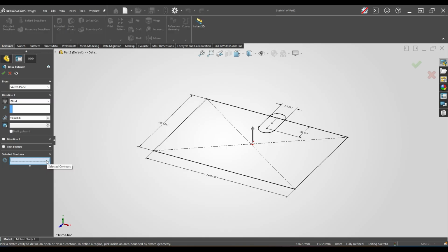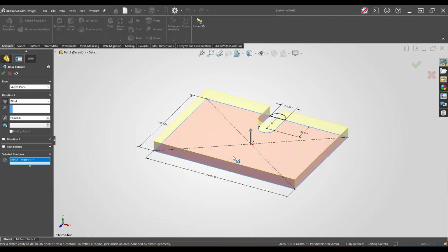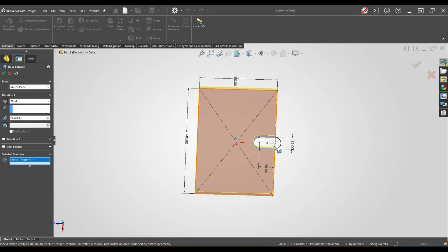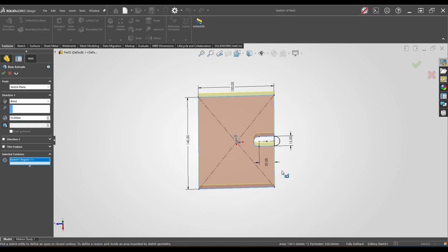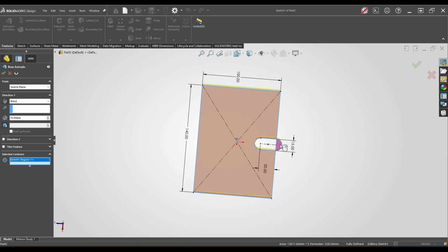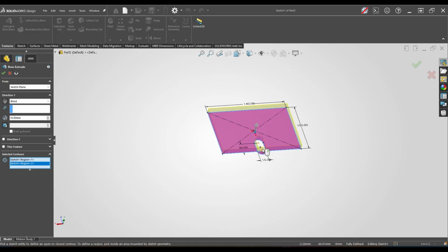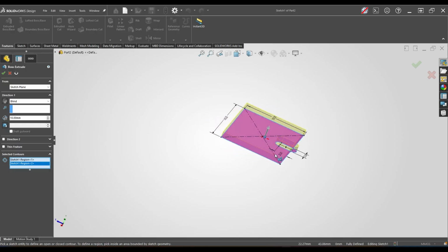gave me that option. I could choose to just extrude parts of this slot, this one or this one, and see how that line there separated the slot out, or, which is what I'm going to do, extrude the main base here. And if you notice, what it's showing me in the preview is that that slot is being extruded, and that's fine. I could even do something weird if I wanted to. Choose that too. And now I'll have this piece extruded, but not that little center.